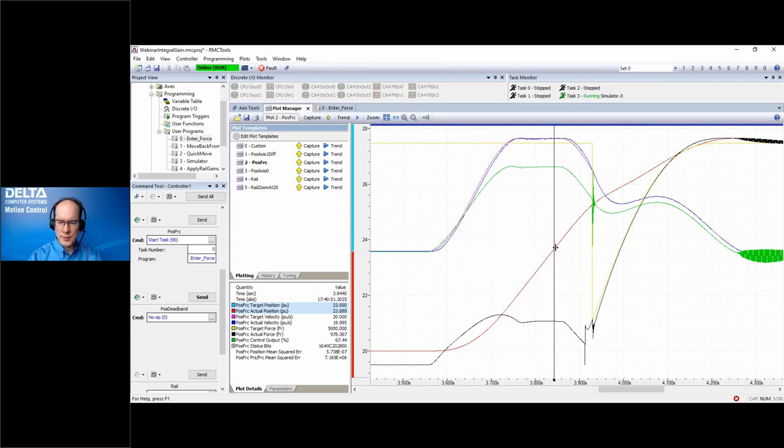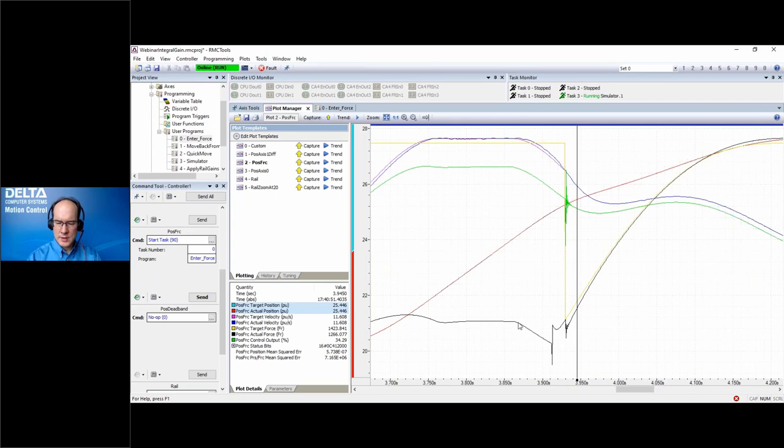It's moving up, and you see that our velocity starts slowing down, and then we see the black line here, that's our actual force, so it kind of does some goofy stuff, but once it reaches 1,000 right here, then we switch into force control. So this yellow line here is actually our target force. It's not the integral term now. This is a target force.